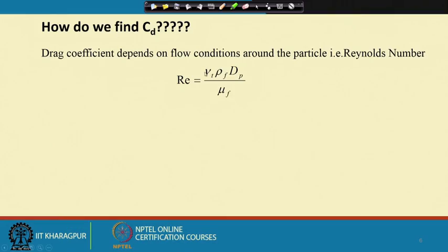With the change in temperature, the viscosity changes, and these values can be easily found for common fluids in a standard textbook of fluid mechanics or many other books. V_T is the terminal settling velocity, d_p is the size of the particle, and rho_f is the fluid density.